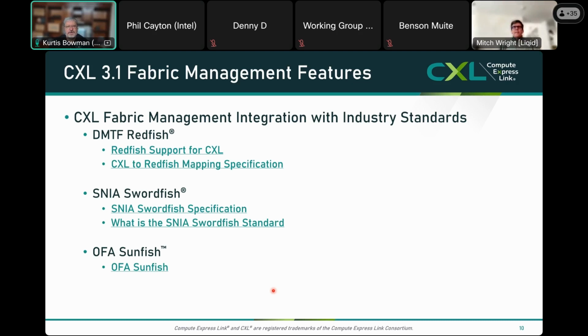So what CXL allows you to do is add that capacity. When you add capacity, you also are adding memory bandwidth. And so you reduce the load on the local memory on the DDR channels. When that happens, if you have super busy DDR channels, you actually can drop your overall latency in the system, as well as you start to realize that performance advantage of having more memory bandwidth and more capacity.